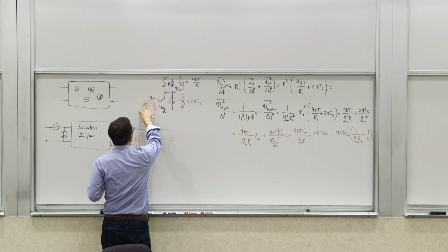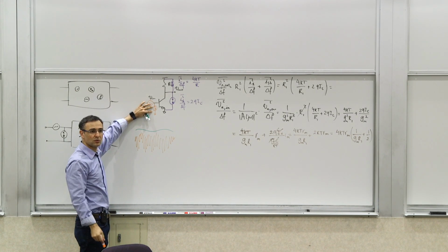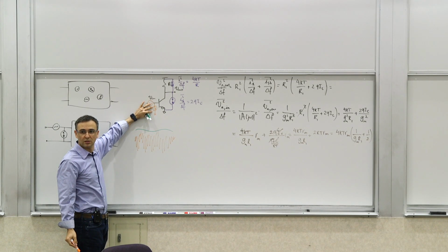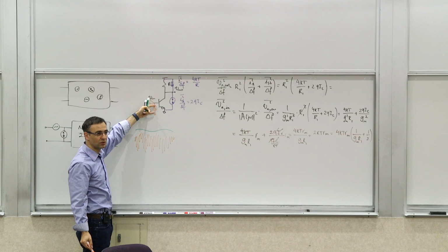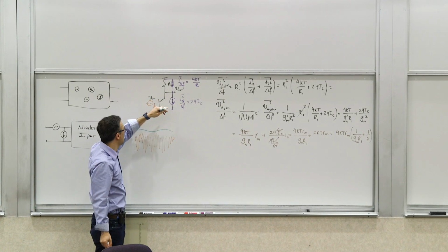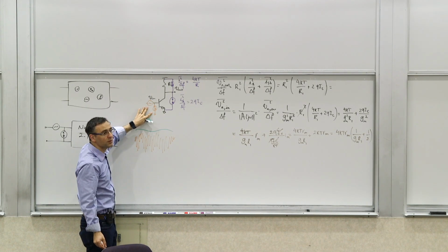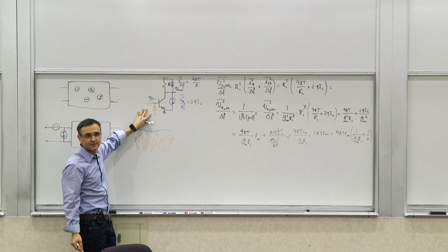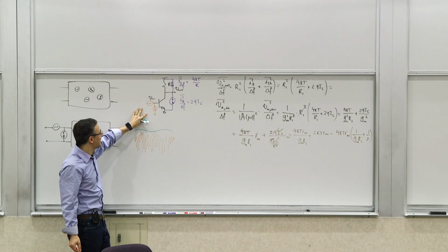When it's in the two ends of the spectrum, when it's open, this current source is producing some input noise at the input. That's where the noise will appear, the noise at the input that would get to the output. And if it's short-circuited, it's this guy that dominates. And if you have some other impedance, other than 0 and infinity, both of them will contribute.